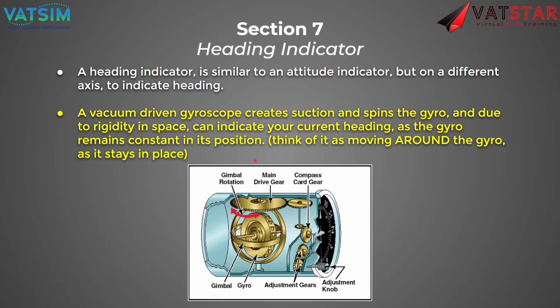What's over time? Is it like an hour, or is it like months, days? What do you mean? Yeah. By over time, every gyroscope is different, but it's typically between 15 minutes and an hour. Every gyroscope is a little bit different. The saying among pilots is they either drift all the time or they don't drift at all. It just depends on the quality of the gyroscope. But between 15 minutes and an hour, you will have to reset the card based on magnetic heading.